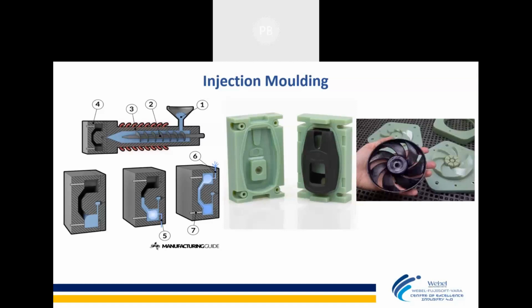In injection molding, 3D printing plays a very vital role nowadays. With a 3D printer, you can develop the initial mold, because after developing a mold, they go for a trial stage, a production known as T0 production, trial production, where they develop 30, 40, 50 pieces to see the quality of the part. Is it up to the mark, or do they need to do some modification in the mold? Are my molds performing in the right way? That kind of dimensional things they check.